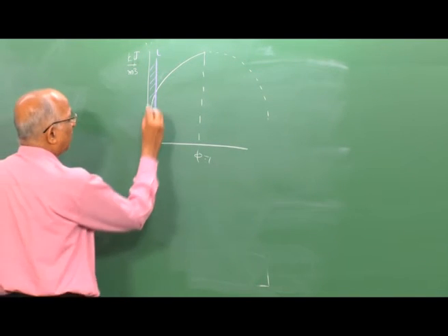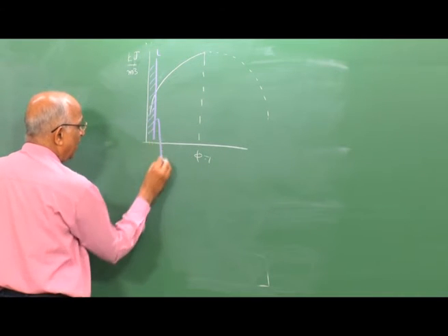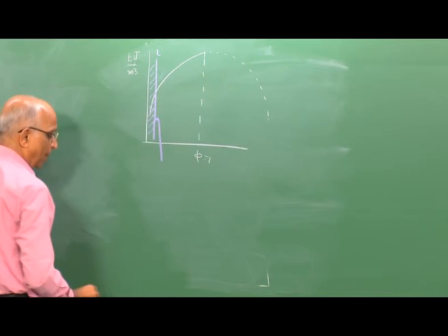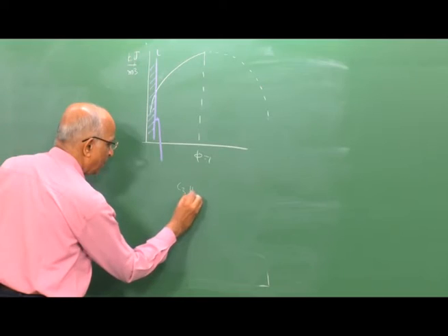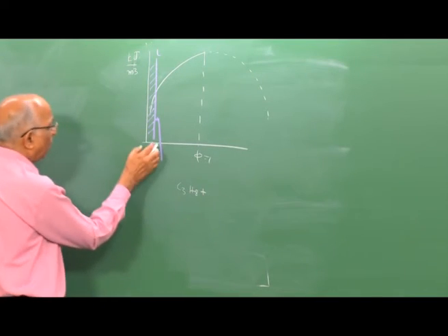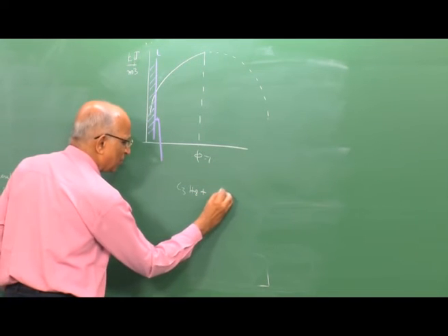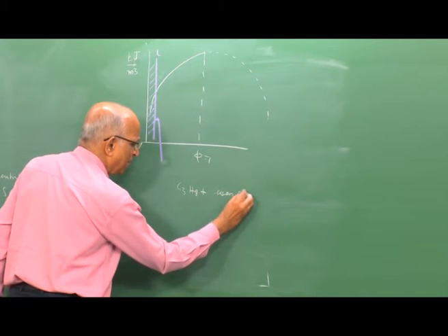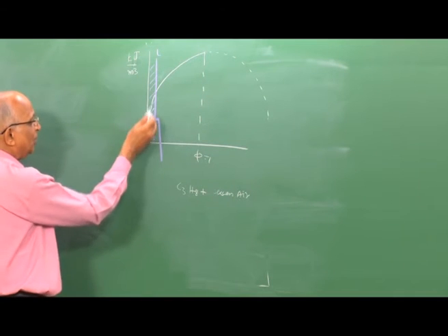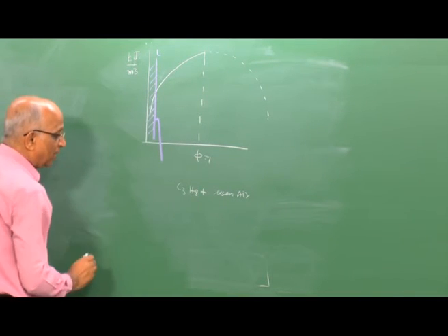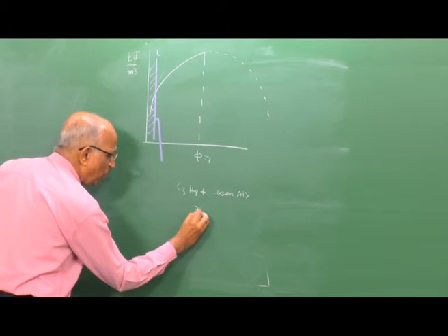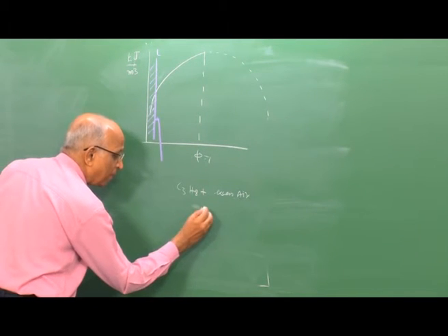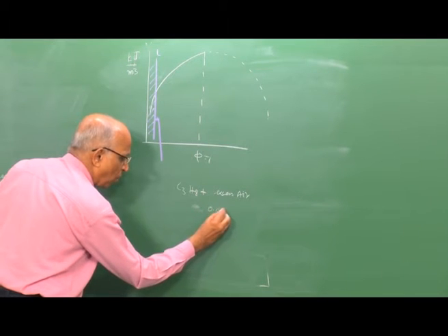Now, what is happening? The heat which is generated over here corresponds to the reaction, let us put it down: C3H8 plus, over here I have excess oxygen, excess air, and this excess air acts as a diluent and brings down the heat of the reaction. Therefore, the lean limit corresponds to 2.1 percent volume, that is 0.021.